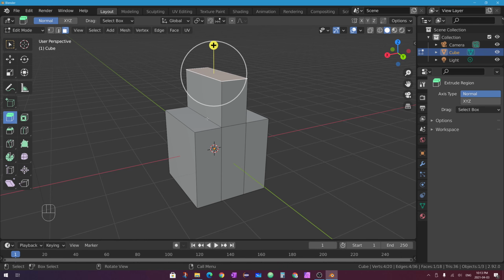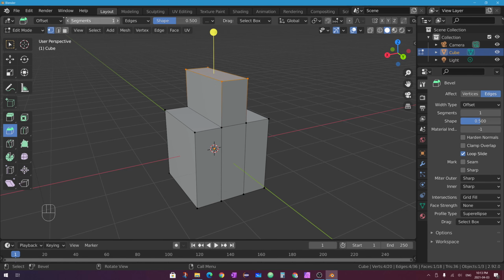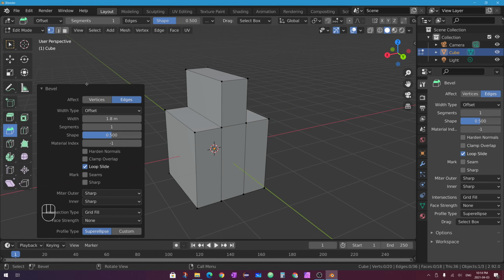Now, you should also be aware that with the Bevel tool, you can not only bevel edges and faces like I've already done in this video, you can also bevel vertices. If I go over to the Bevel tool and then go into Vertex Select mode, and I select a vertex on the corner, which will probably work better for this example, of a mesh, if you pull on the gizmo handle of the Bevel tool, well, by default, nothing will happen because the Bevel tool really has 2 modes. Edges mode and vertices mode, and this is called the effect mode.